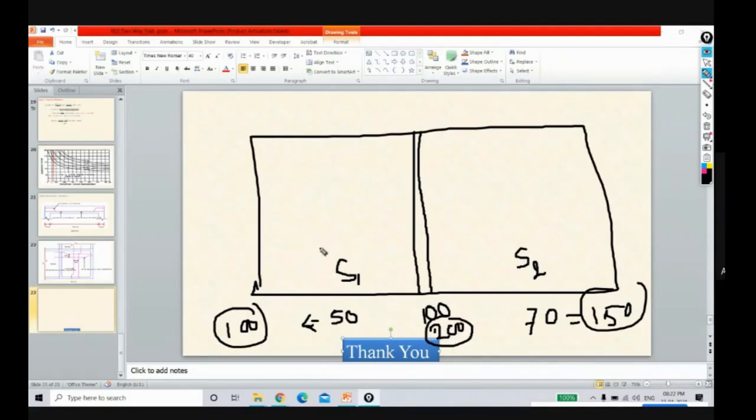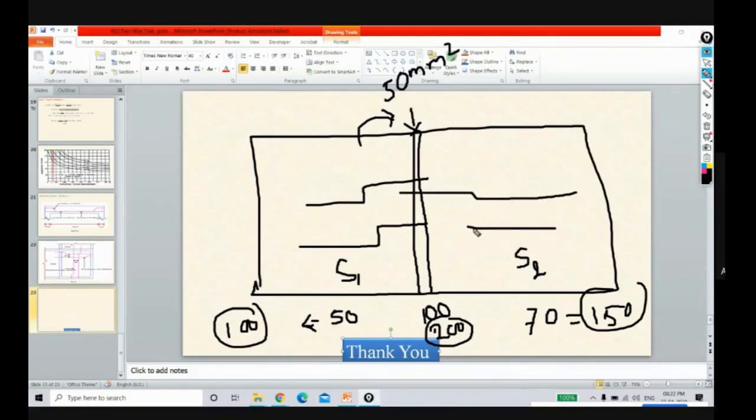If we use the bent up bar for this slab, already 50% reinforcement we are providing over here, alternate bars. So at this edge from this slab we have already provided 50 mm² reinforcement. Again, alternate bent up bars are coming from this side, and again 50% reinforcement, which is 75 mm², is provided. So due to the continuity for S1 and S2 slab, we have already provided 125 mm² reinforcement at this edge, but our requirement is 200.